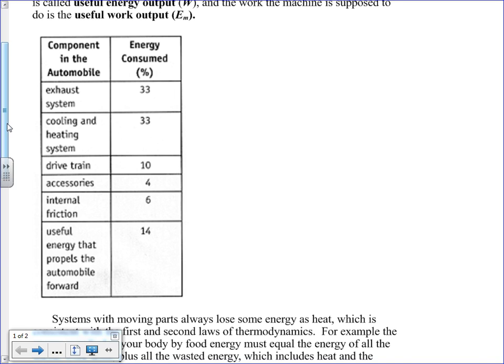There's just so much heat in those spent gases, and they're not doing any useful work. Your exhaust does not propel the car forward. So that's lost. 33% right there. You have not moved forward yet. 33%. All right, cooling and heating system. $33 out of your $100 worth of fuel. Your car is so inefficient. It needs to use 1/3 of the energy you put into it to keep it from melting down.